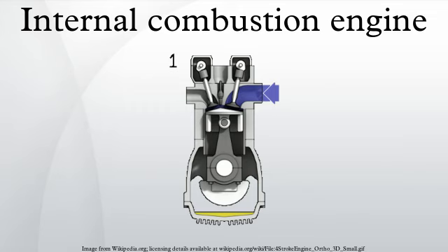Intake and exhaust ports are ports that carry fresh fuel-air mixture into the combustion chamber and products of combustion away. Crankshaft, a shaft that converts reciprocating motion of the piston into rotary motion. Connecting rod, a rod that connects the piston to the crankshaft. Spark plug, an ignition source in the cylinder head that initiates the combustion process. Reed valve, fuel air check valve.